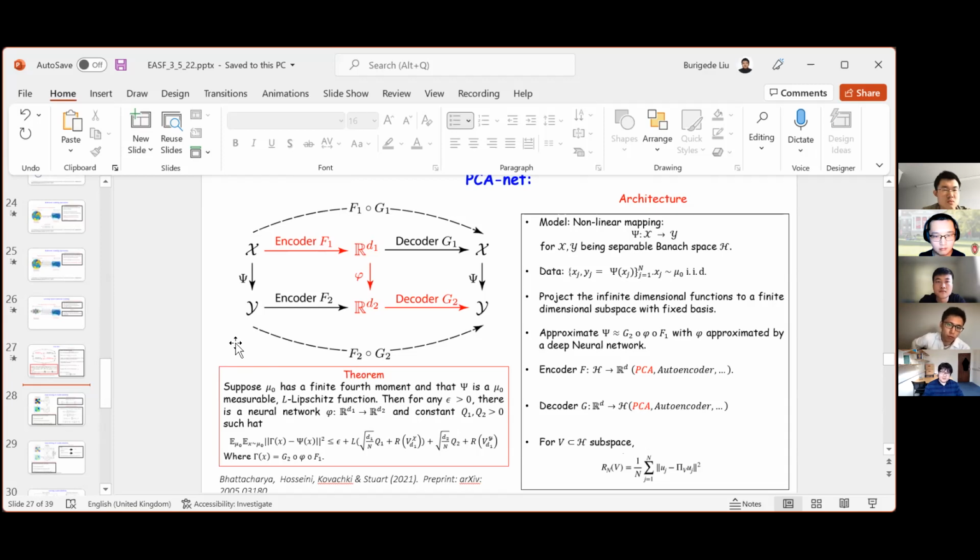The key thing here is we're going to project to the same PCA basis. So the data resolution can change, it can change whatever they want, but nevertheless, we're going to project it to the same PCA basis. There's a way to do that: you can fix the PCA basis. By doing so, you can achieve resolution independence, basically by saying that I only need to train a neural network here, and all the encoding and decoding process can depend on PCA.